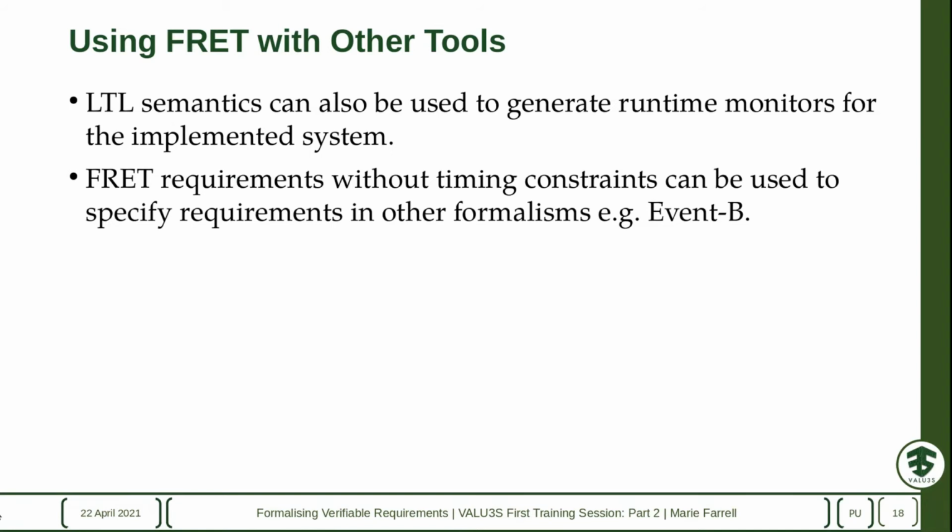So, of course, LTL semantics, as I mentioned earlier, can also be used with other tools to generate runtime monitors for the implemented system. And we actually did that in a prior project. We used the FRET requirements to generate runtime monitors for a robotic arm, and the runtime monitors were incorporated into the robot operating system implementation in Python for the system. So it was full traceability kind of from requirements to implementation monitors.